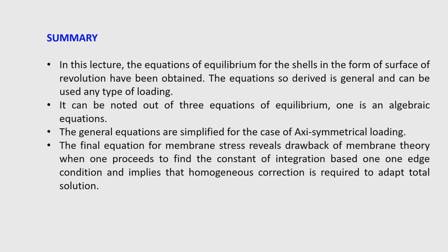So, when the differential equation is solved, then we can find this value of n phi, and substituting this value of n phi in the second equation, n phi by r 1 plus n theta by r 2 equal to w r, we can get the second stress, circumferential stress n theta, because in case of axisymmetrical loading this n theta phi is 0. So, only two forces are of importance, the one is n phi and another is n theta.